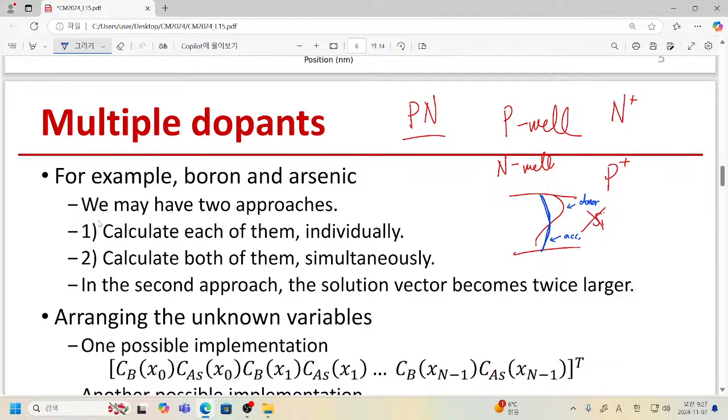That's not the case. If you apply certain heat to your wafer, then all of your dopants are moving. Even your host material, silicon, is moving. Of course, since the atoms are identical, although they are exchanging their positions, we cannot actually see their movement.